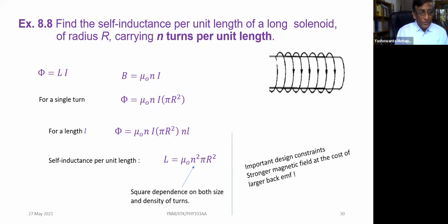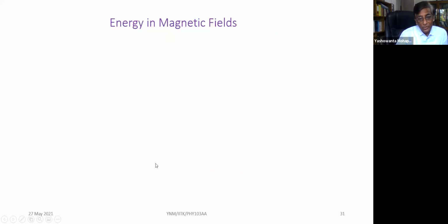I hope you have tried your hand at winding an inductor. It's so simple to do. Copper wire is easily available; take a cylindrical shape and turn it, and you can do many experiments if you take care of back EMF. Actually, back EMF can be very nasty and can give you a shock if you don't take proper care.